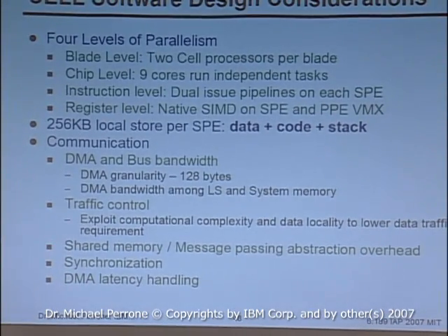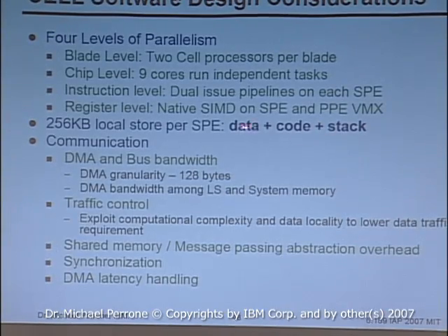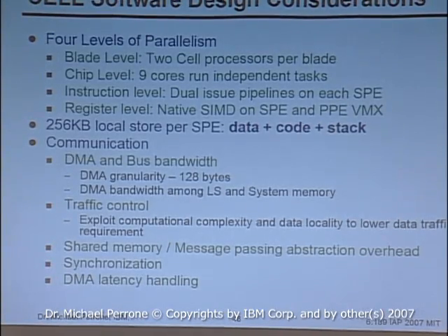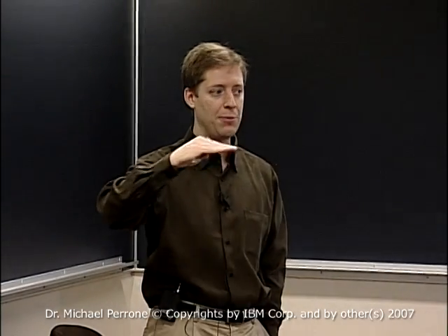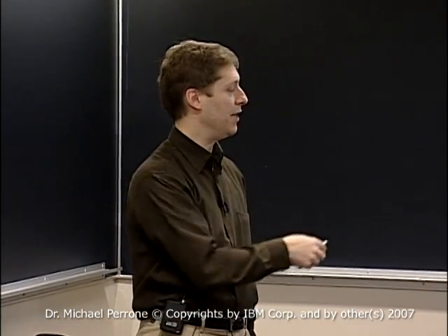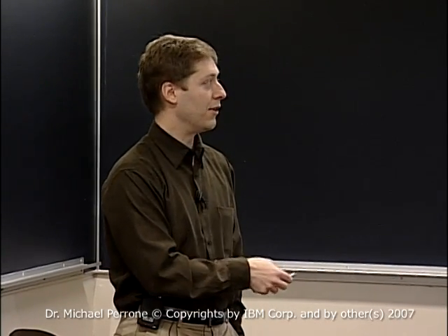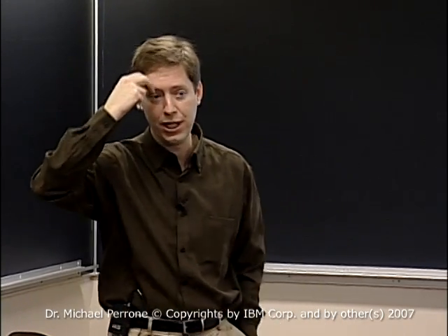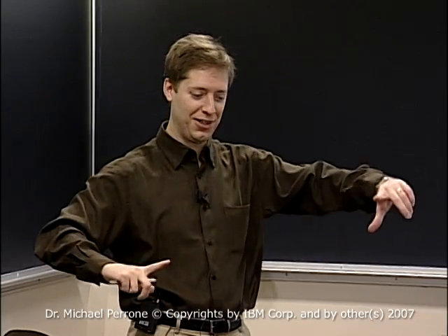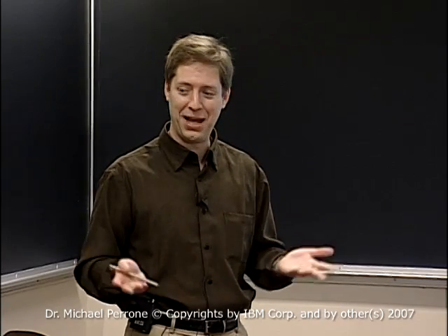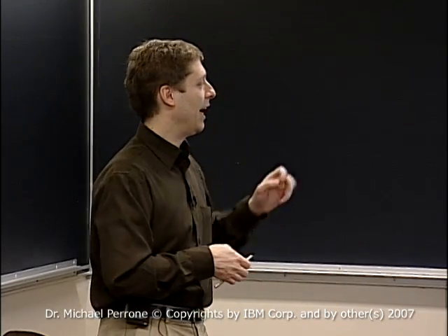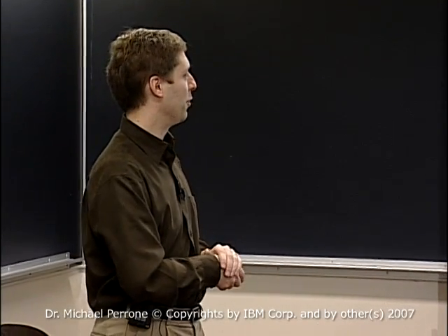Now, there is a memory management library, a very lightweight library on the SPE, and it's going to prevent your data from overwriting your code. Once the code's loaded, that memory management library knows where it is, and it will stop you from doing a malloc over this code. But the stack is up for grabs. That was done because of power considerations and real estate on the chip. If you want to have a chip that's this big, you can have anything you want, but manufacturing it's impossible. So things were removed, and that's one of the things you have to watch out for.